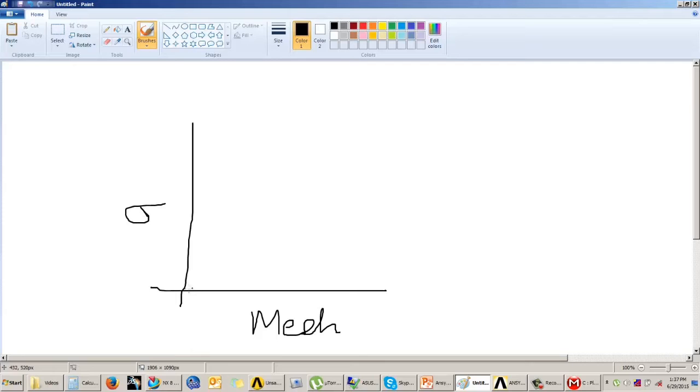Okay. We have a stress value. Now we go on refining the mesh. As you refine the mesh, the stress value will increase. But after a certain point, the stress value will almost become constant. It will not increase any further. So from this I can judge that this over here is the optimum mesh size. I should not further refine it because the answer is almost going to be constant.